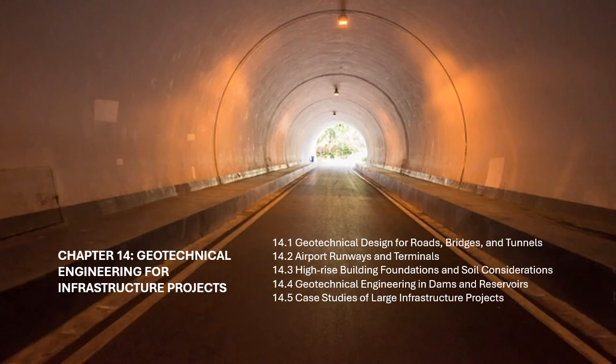Geosynthetics are now commonly used to reinforce runway subgrades, enhance soil bearing capacity, and reduce the potential for cracking in pavements. Intelligent compaction and monitoring. Advances in intelligent compaction technologies enable real-time monitoring of soil compaction during construction. This technology allows for better control of the compaction process, reducing the likelihood of future settlement or deformation.